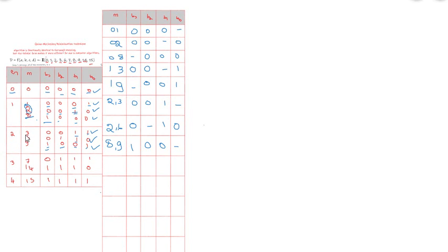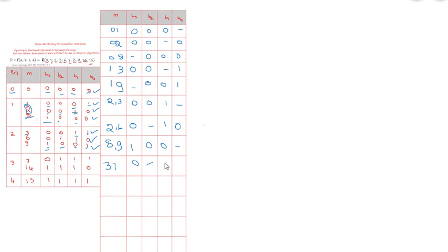Now in this we have 3, which is 0, 1, 1. Is there any group having last bits 1, 1? Yes, in the 7 the last bits are 1, 1. So we will go with the 3 and 7 grouping. So 3 and 7 grouping is possible. In this the last bits 1, 1 are the same, but B2 is 1 in 7. So we will make it 0 bar 1, 1. That means only B2 differs in 3 and 7. All others are the same. Okay.